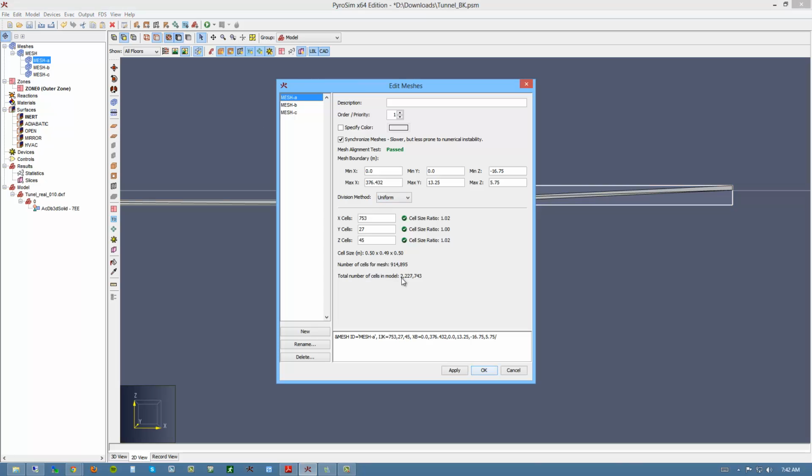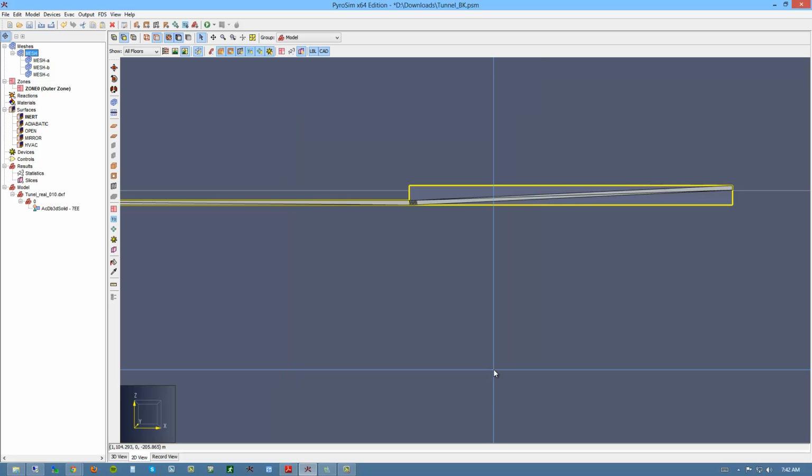of meshes in this model, we reduced that by about 1 million grid cells, a little bit more. So we were at 3 million something before, and now we're at 2.2. So we've reduced pretty nice. So that's a gigabyte of memory we've just saved by just pulling that center piece down. So that's the way that you can do refinements, splitting, and coarsening meshes.